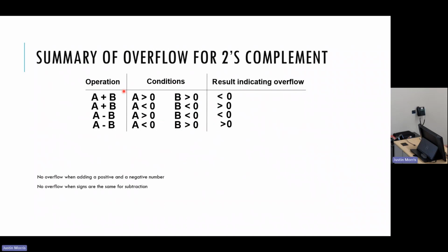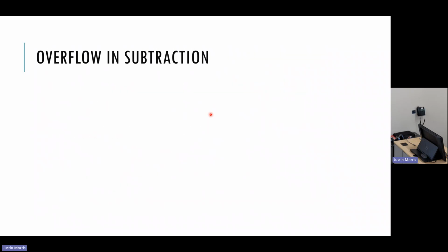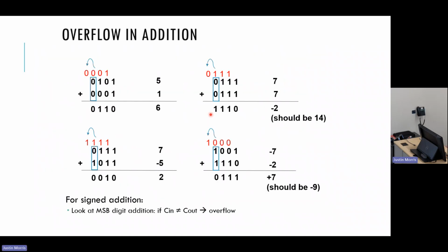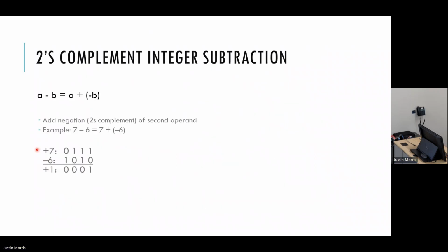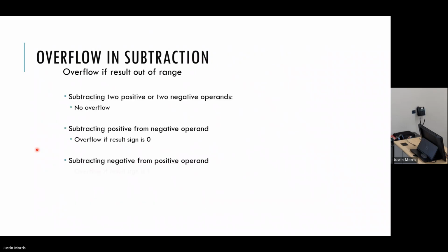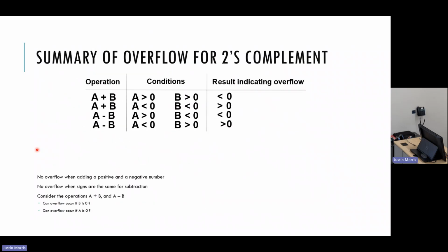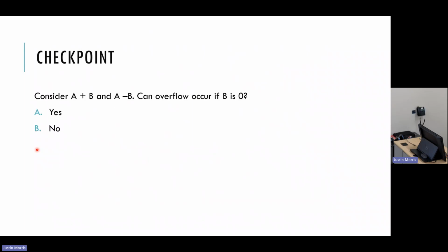But again, this is the more complicated way of detecting overflow. For addition and subtraction, the XOR works. This is what is implemented in hardware because it can be checked with one simple gate. So that is addition and subtraction.